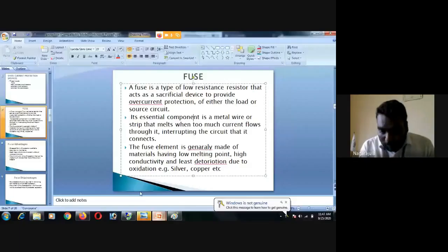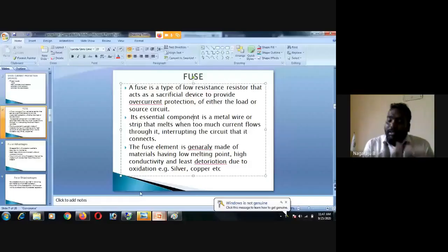Power fuses are employed where the system voltage is 34.5 kV or higher, where the interrupting requirements are greater than the available fuse cutout ratings, above 600 volts, in the subtransmission level of 34.5 kV. So where you have a higher rating, you can use these power fuses.